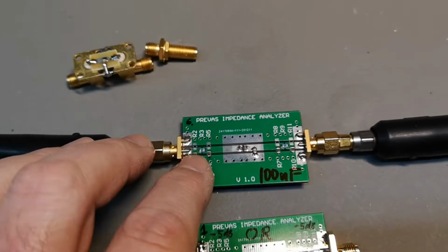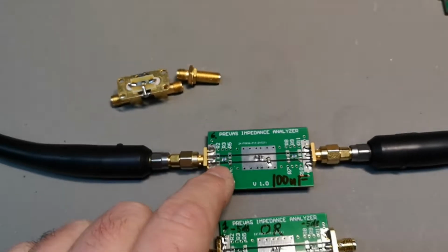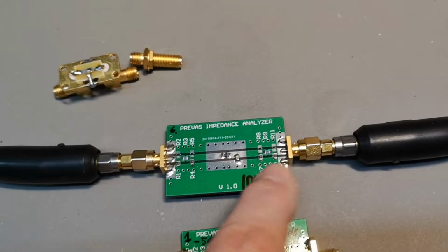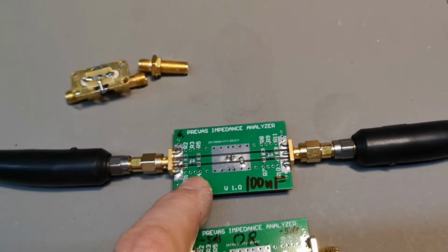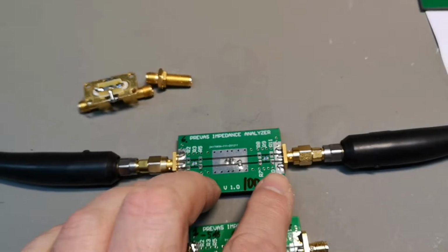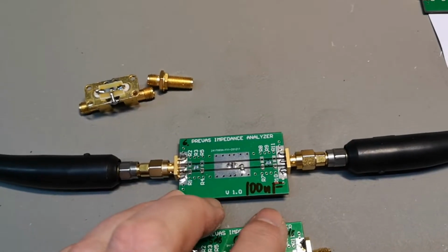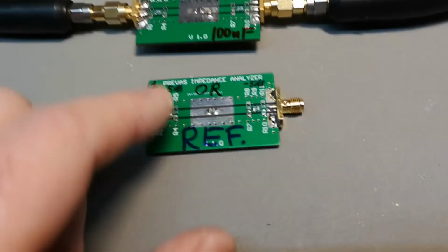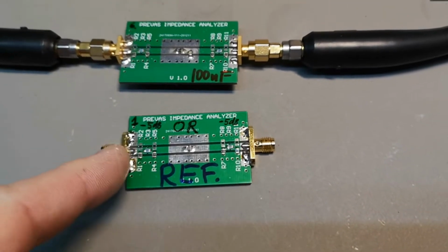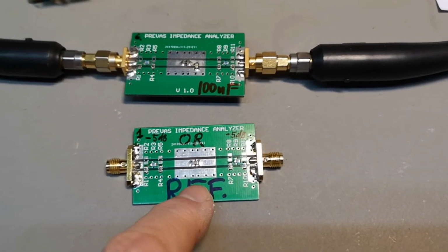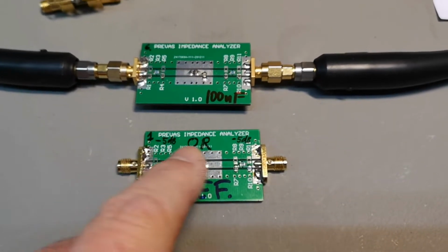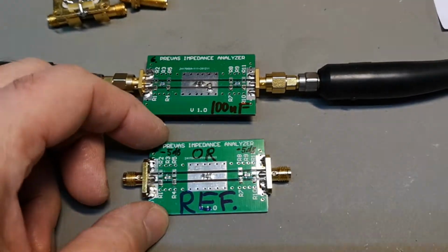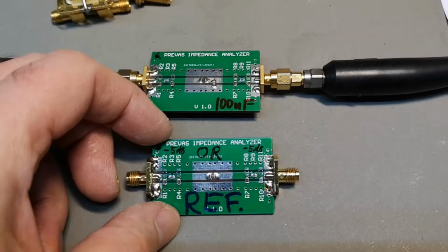Because this will eat 5 dB of the power, and this will eat 5 dB of the sensitivity. 10 dB is very smart because it's easy to see when we go into the tracking generator menu, and we will see that we have a flat 10 dB loss from 0 to whatever the analyzer can do. This just proves that this device is flat in response, and it has the right impedance and is working.